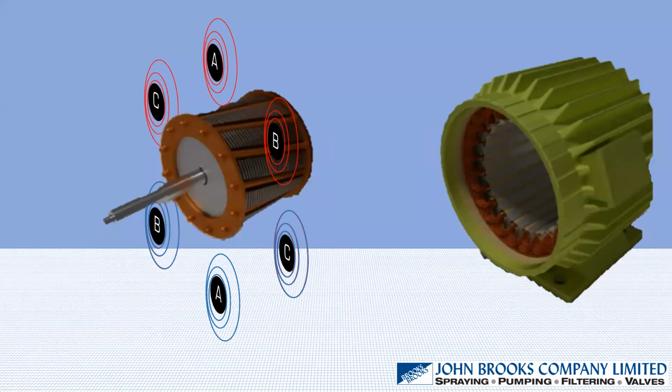And if you remember here, the C, A, and B at the top are all in one phase, or one induction type. We're in the north or south, whatever the red was. And at the bottom, we're in the opposite, the north or south, always the opposite. And what we're going to do is induce a current in those bars of that rotor.